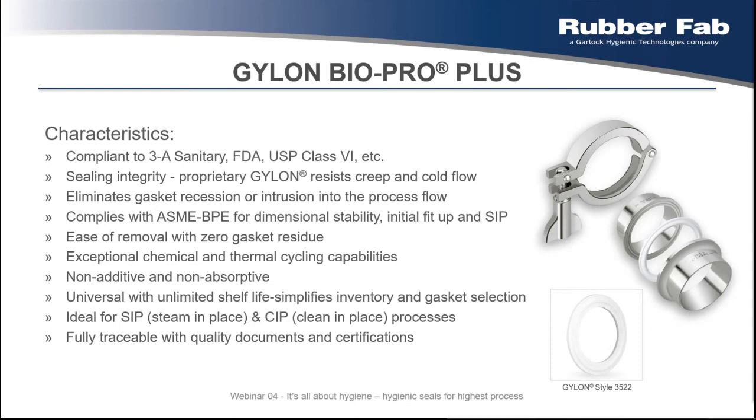So it complies with the ASME BPE on dimensional stability requirements, which are laid out in the standard, initial fit-up requirements, again laid out in the standard, and it was SIP tested according to ASME BPE. So the steam resistance was tested, and also the dimensional stability after long-term exposure to steam. So test results are available. We're happy to share them with you.